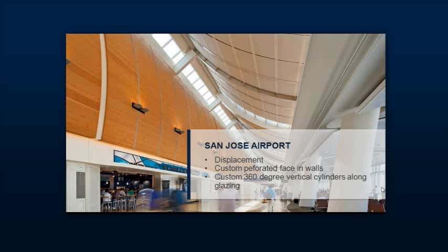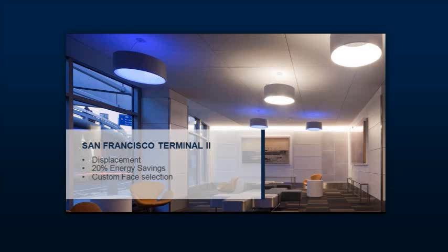Underfloor. Underfloor air is typically supplied through a raised access floor. Although it can be individually ducted, the most economical one is a pressurized plenum. And you can see in the bottom, we have this dashed line drawn across above the occupant's head. This is what we consider our design point, where we try to thoroughly mix or optimally mix in this space up to 6 feet above the finished floor.